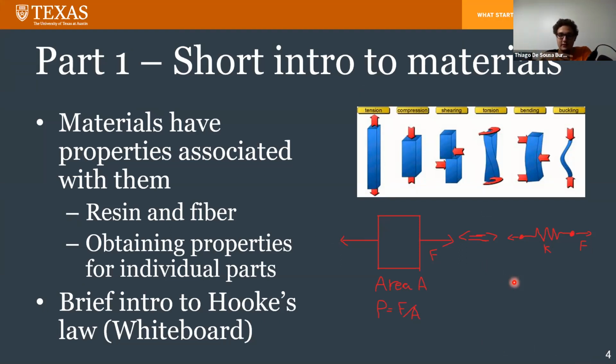It's very different in the case of composites, because composites, as I will probably cover later on, don't have the same properties in basically any of the directions. You can estimate it to have 3 directions that have the same properties. But even then, that's an approximation. It's not true. But in order for us to be able to compute anything, we have to make some assumptions.